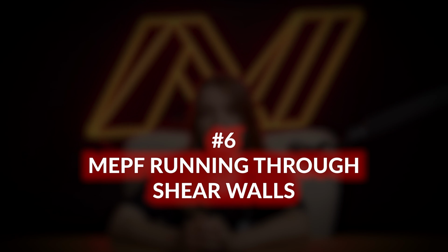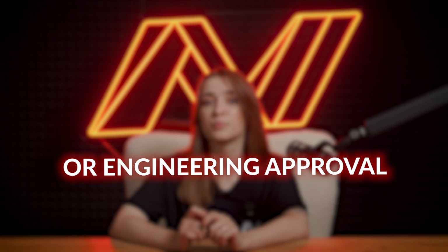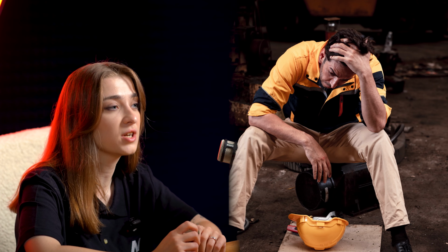MEPF running through shear walls. Shear walls resist seismic and wind loads. They are critical. Yet we've seen MEPF systems routed through them without reinforcement or engineering approval. This isn't a minor mistake. It compromises structural integrity, triggers redesigns, and can even lead to project shutdowns.